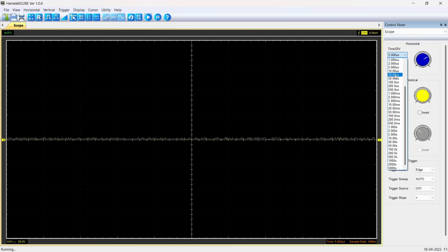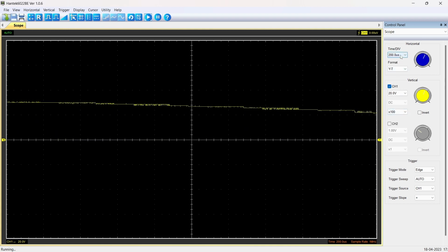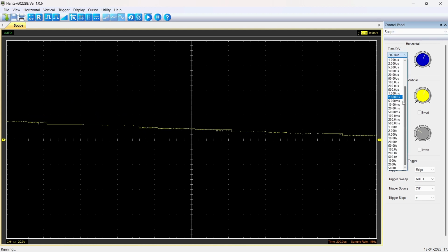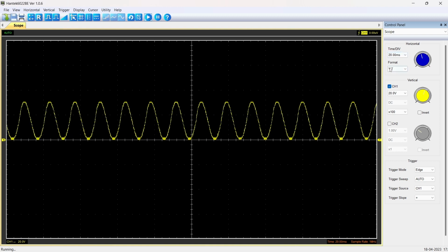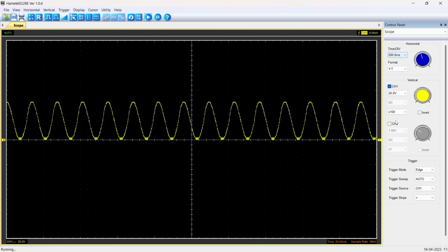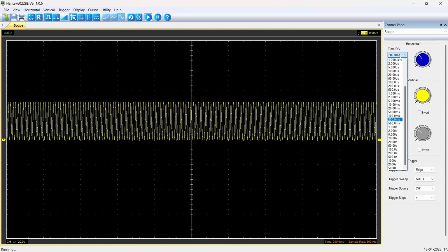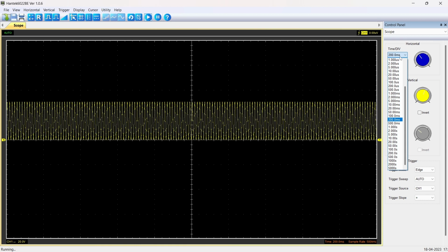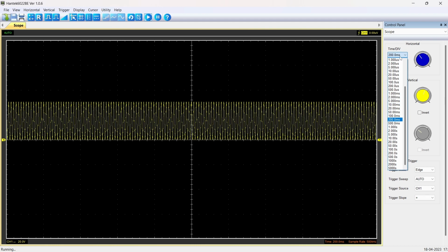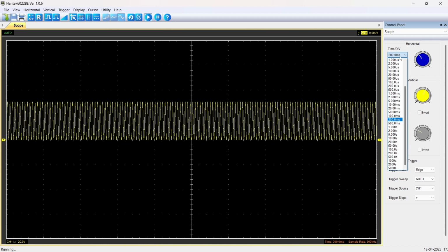So we have to add some delay here. Okay. So you can see as per the delay, the sine wave is been changing. Okay. So when I give those 20 milliseconds of delay, so I can get this exact sine wave. So I will increase this delay. So by increasing this delay, you can see this. So this is how we will create the sine wave, and this is how the DAC is sending the data to the speaker, and by varying this voltage only, the speaker is generating the sound. Okay.